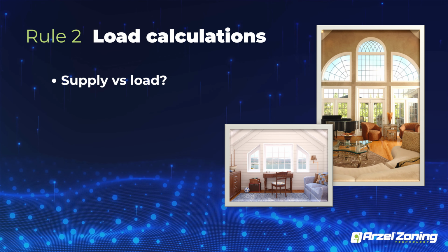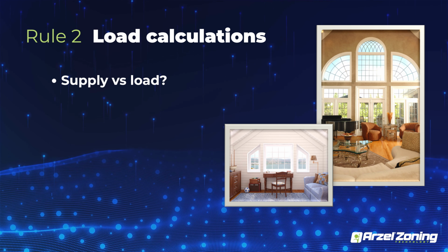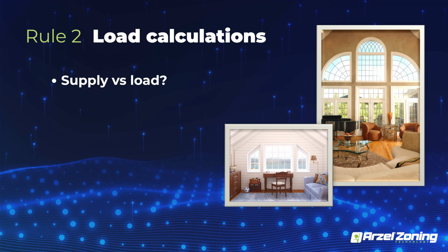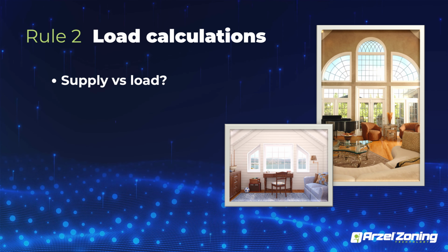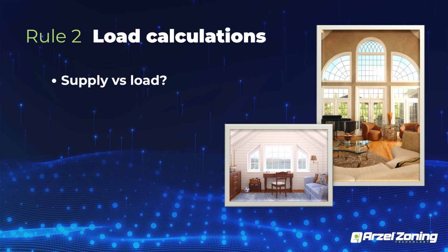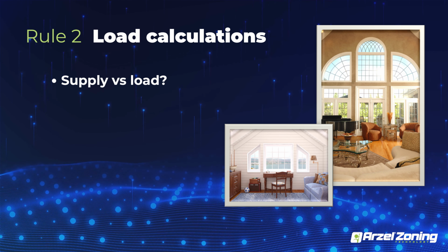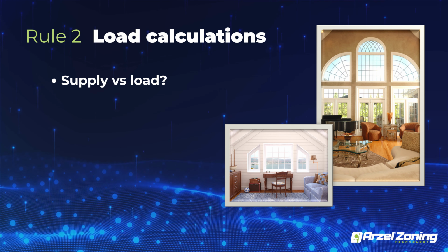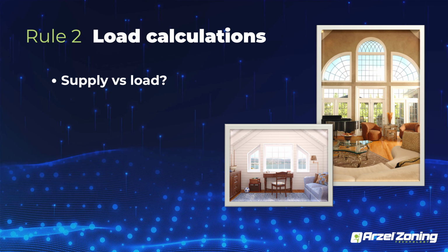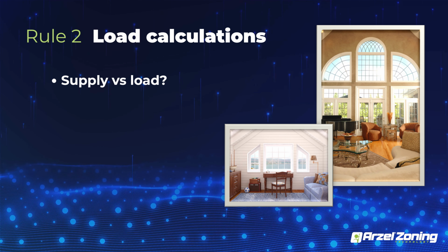Now, I've seen attic spaces that were built out to be a bonus area, and the contractor could only get 1 register because everything's finished downstairs. He couldn't run ductwork, and he put 1 register that blasts into the room, and then he applies zoning to it, assuming that with 1 supply, but I put zoning on it, give it a thermostat, I'll be fine. No. You're overestimating the power. You still need to have the right amount of ductwork into a space.